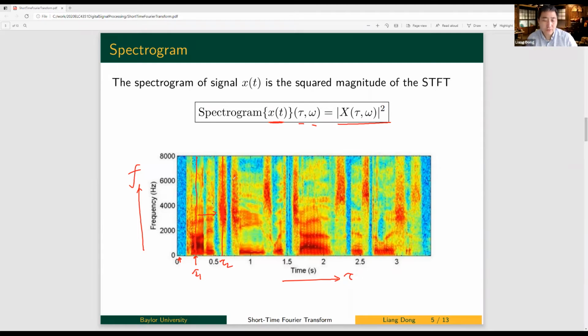And you don't have to wait for all the signal coming in. As sufficient signal comes in, take a short-term Fourier transform. And then new data come in and you shift the window and continuously perform this short-term Fourier transform and get the spectrum result. And it will be a dynamic rollout spectrogram. Okay, so it's very nice.